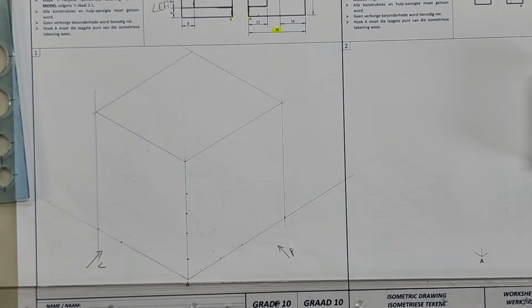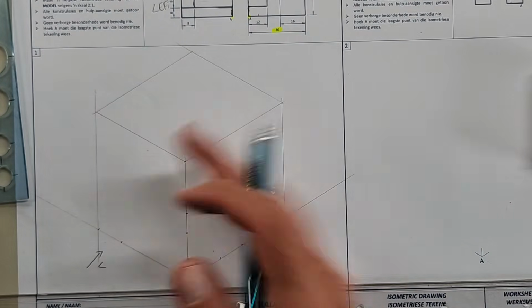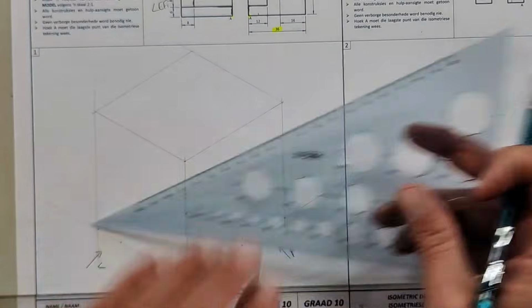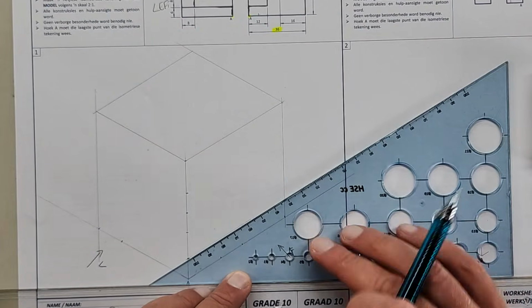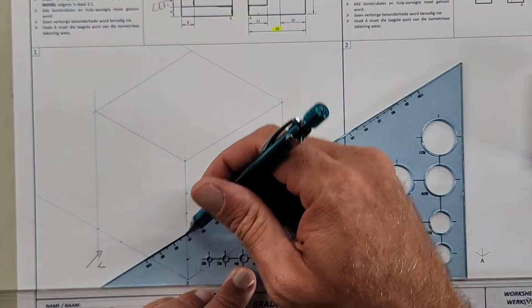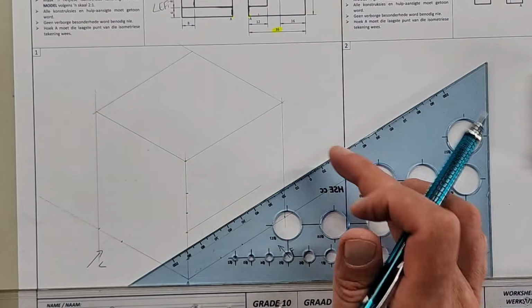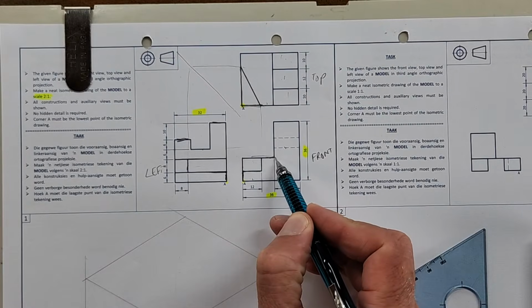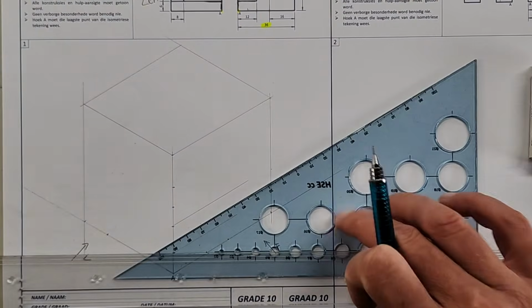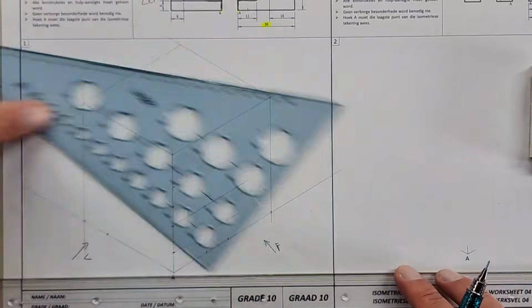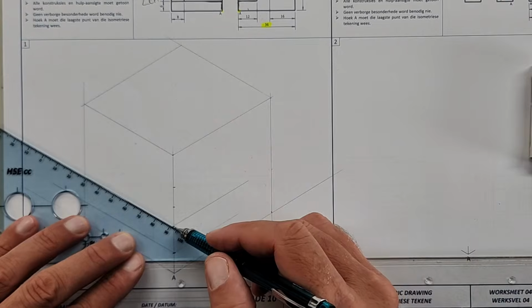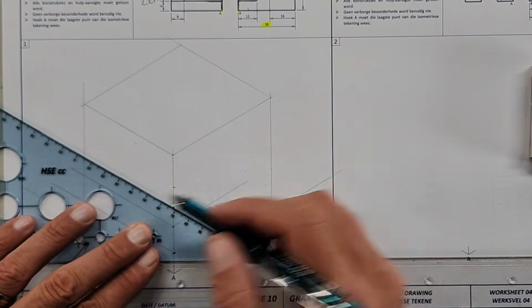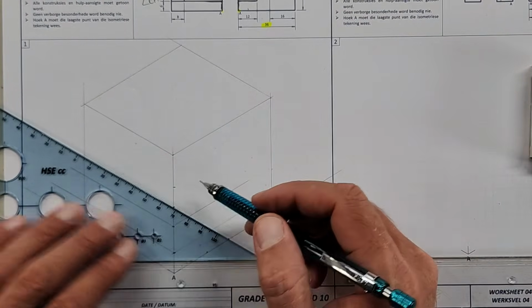Now we've got the glass box, and now it's just using what is given here. The heights are important. I'm going to copy them to either side, especially here. That 6 is going to be important, and then here that 8. I already know this line isn't going to go all the way to this point, because look here, it's this line. So I just draw it in construction to where it's going to end up. That helps me not to be too confusing. On the left hand side, it does go through all the way, as well as this one. And then there's a height of 6, which is here, and that one there.